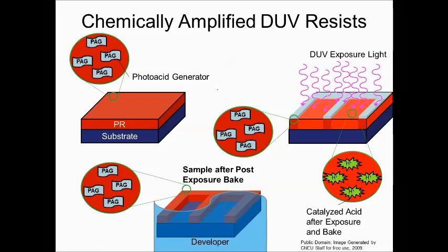And that starts the step. And we can do that in like a second. Does everybody see that? But the process is not finished. It's just started. Then what we do is we put that on a hot plate, and it finishes that process, because chemical properties are often completed and understood with the concept of the Arrhenius equation, right? And that's basically e to the -E/kT, where k is Boltzmann's constant and T is temperature. It's an exponential, and that makes this process quicker. So we're using this heat process to finish this, which was started with light by this embedded photoacid generator.